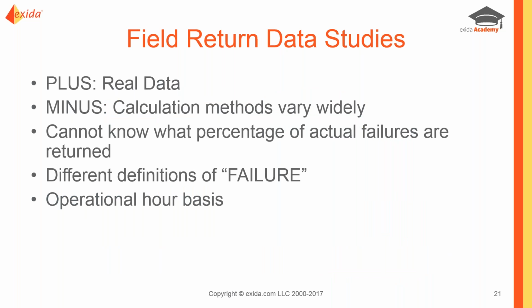Now, field return studies, as I said, there's pluses and minuses associated with it. It's always great to have real data, but you have to understand the calculation methods that are used in analyzing that data to make sure it meets the requirements for why we want it, the data for SIL verification. One of the big catches there is that we don't actually know what percentage of actual failures are returned. Like in the example I gave you before, that was a solenoid valve. Solenoids are inexpensive, so it's likely that a lot of them are simply just disposed of and replaced without ever being returned to vendor. So it could very well be that there is a